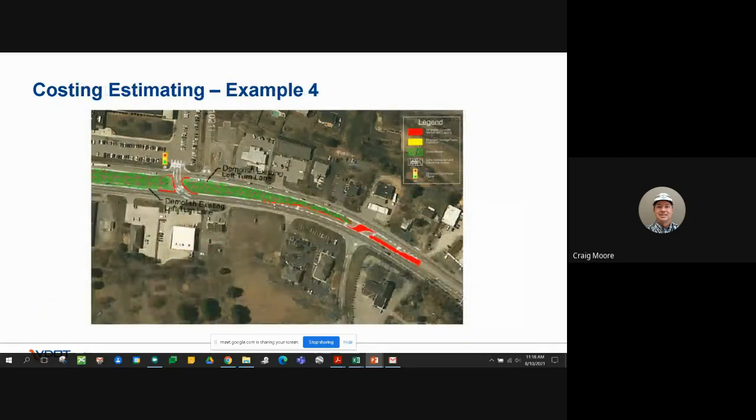Also on the other end, providing another restricted movement with a signal, making it a left only in terms of coming through the median crossover. The signal allows right and left turns, but no into movements from northbound 220. And as we continue along, there's a little bit more work in the median, improving the flow through this corridor and wanting to preserve the arterial movement through here. So part of that is reducing congestion. Again, looking at this, a fairly straightforward type project.